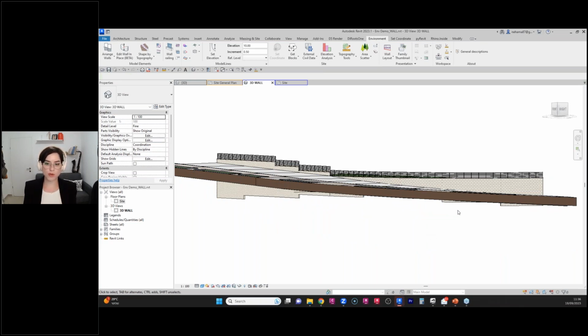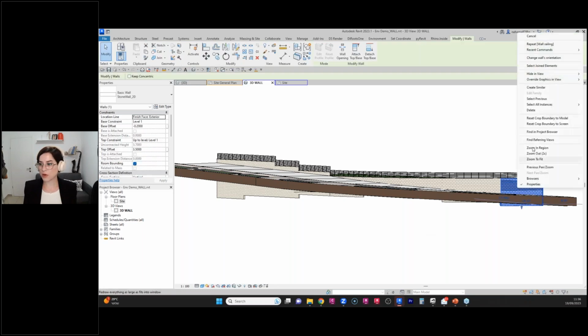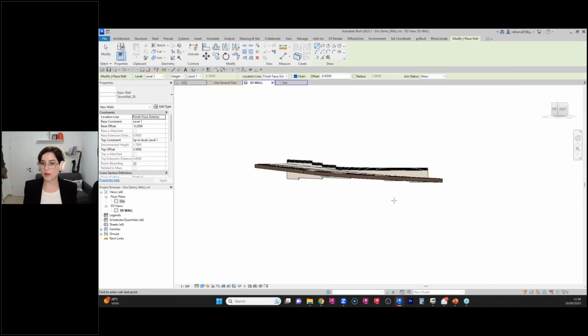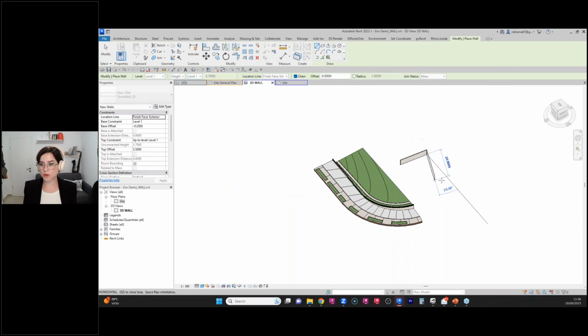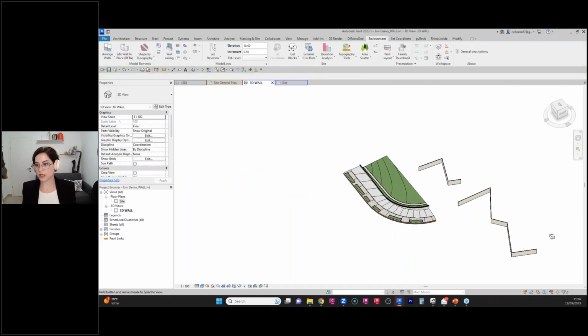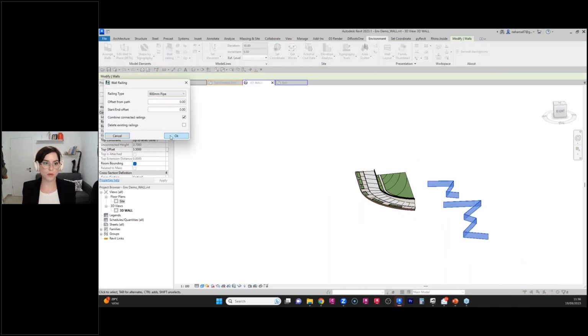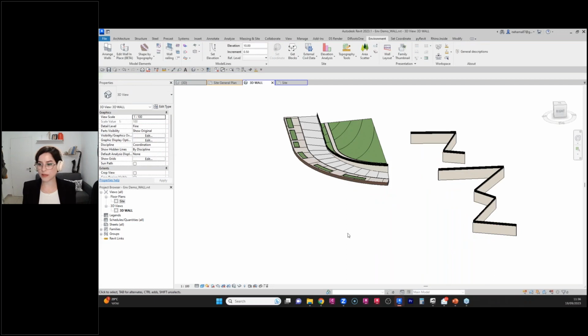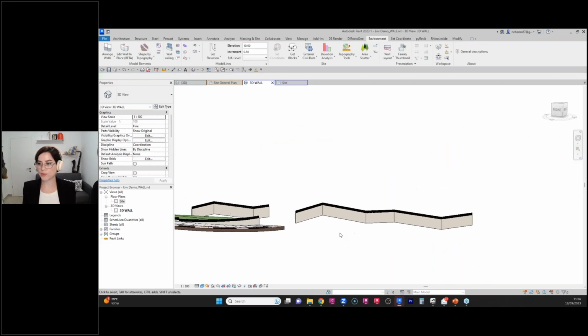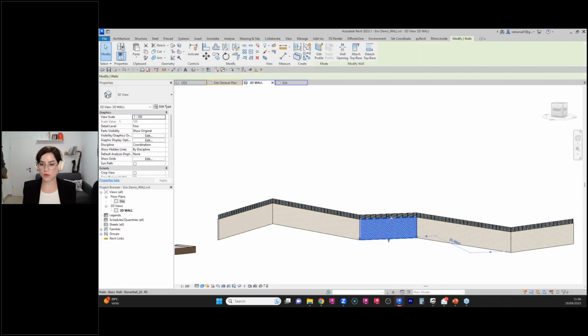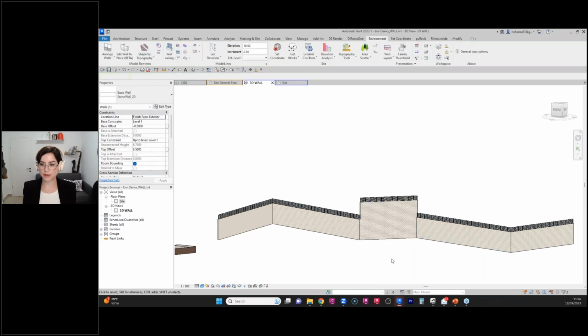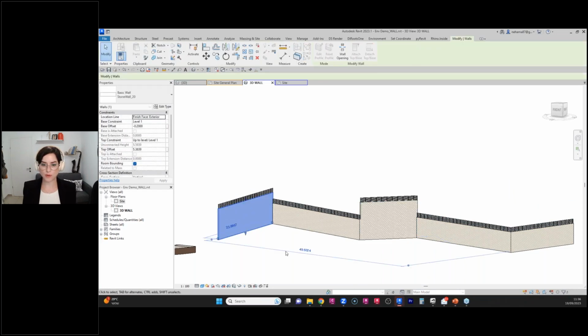If you have a lot of walls, this could allow you to place the railings on multiple walls all at once. So if I have all these walls over here, I could just select them, go to Environment, Wall Railing, and then have railings hosted on these walls. And of course, the railings would update as I update the walls.